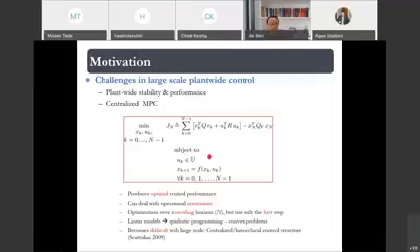We need to optimize the cost function and solve for the control actions over a receding horizon for the next, for example, N steps. The optimization obviously is subject to the model of the process, and of course all the manipulated variables are constrained.